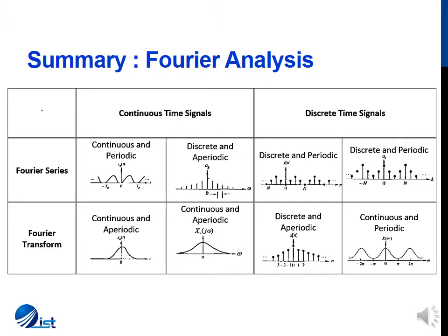And if we plot the phase of the frequency content versus frequency, it is known as a phase spectrum. We also saw that for a real signal, as we'll be encountering in our course, the magnitude spectrum is even symmetric and the phase spectrum is odd symmetric.